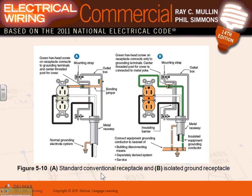Most of the time, one will come from an EMT conduit through the box. That's the dirty equipment grounding conductor. And the clean equipment grounding conductor comes from a number 12, a fully insulated green conductor that lands right into this slot.